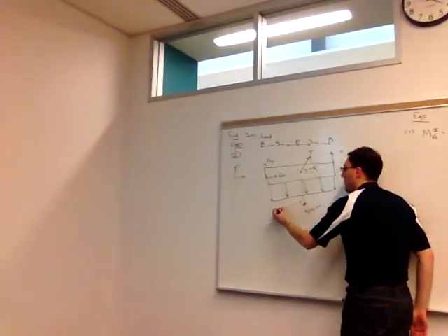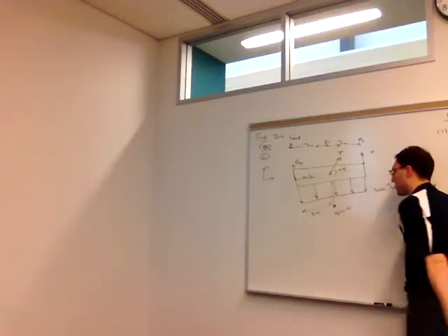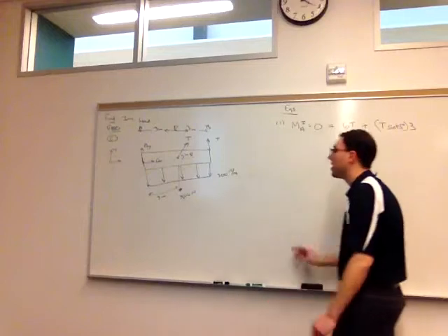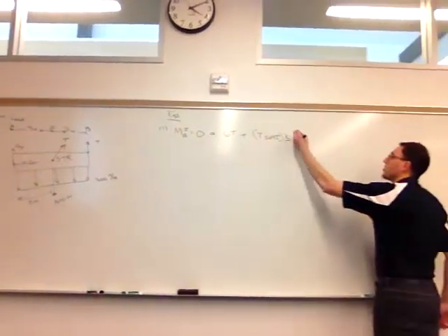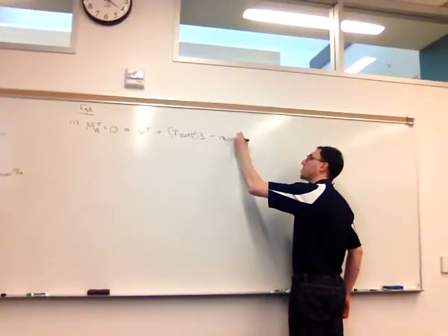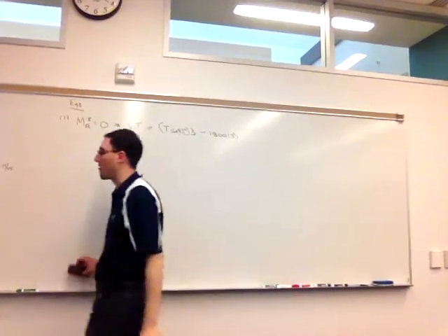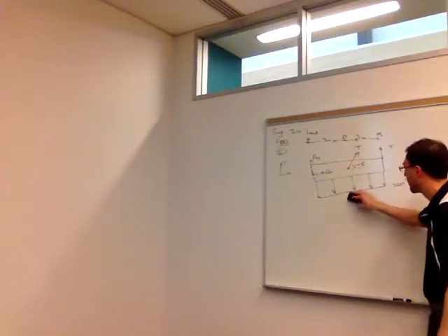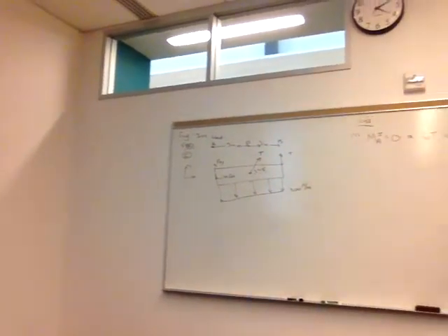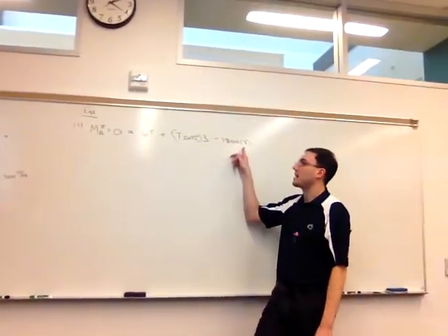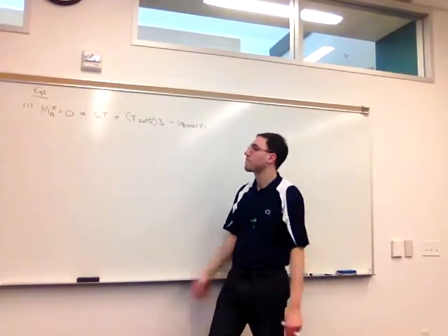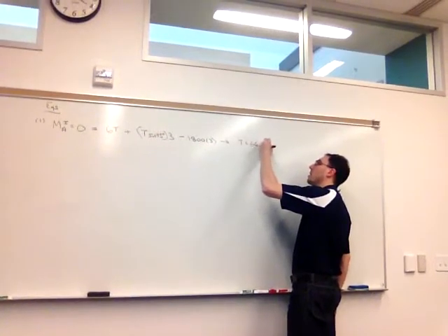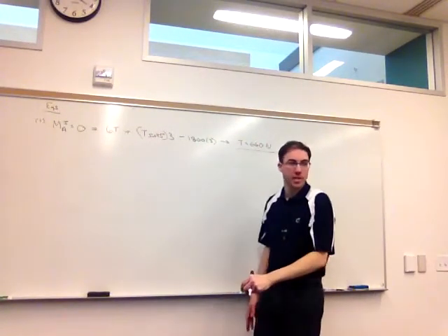And it's equivalently 3 meters away from A. So that's just for our recognition. That's going to be then a negative 1800 times 3. I don't actually want it in my free body diagram, though, or I'm double counting this distributed load. So equivalent force of 1800 newtons acting 3 meters away from point A. From the first equation, therefore, we know the tension is 660 newtons.